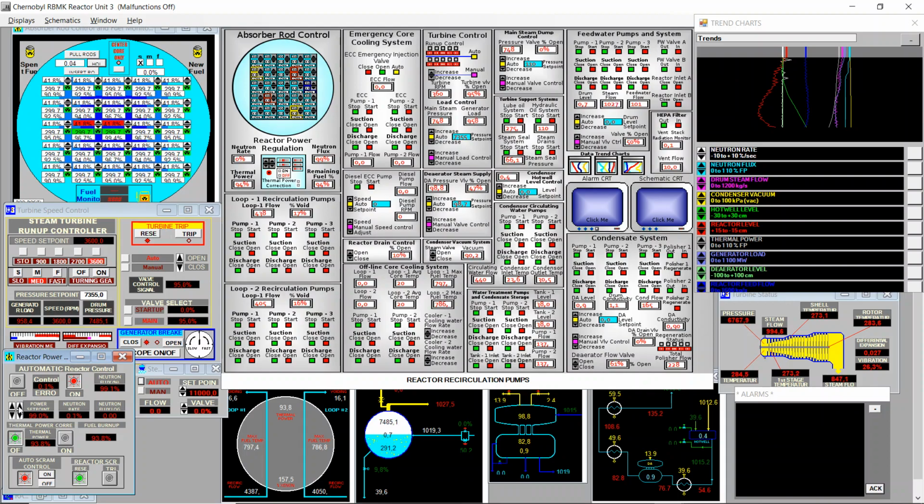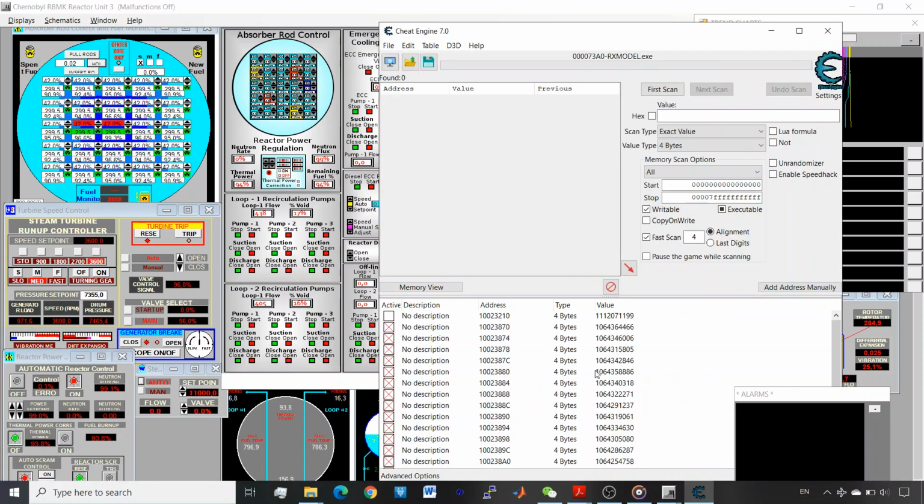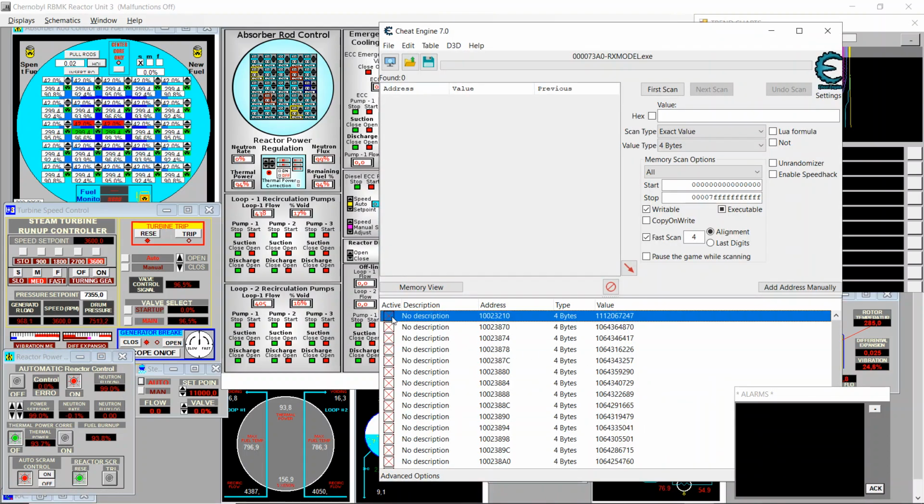So I will go. You see that we have power set point at 99%, but we have neutron flux at 99.1. Why is this? This is because of xenon decrease. If I fix xenon now, we'll see how the power set point matches the neutron flux. I will do it just to show you now. Fix the xenon and you see the neutron flux is 0 because now there is no increase nor decrease of reactivity in the reactor. So what we set in the power set point is what is in neutron flux, because the controller doesn't need to move to adjust it.